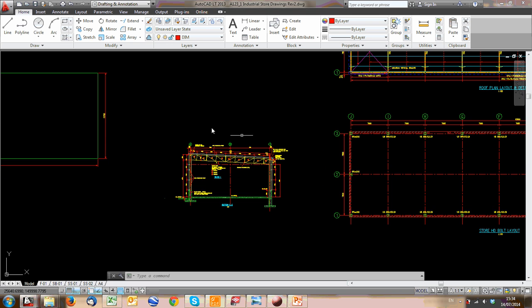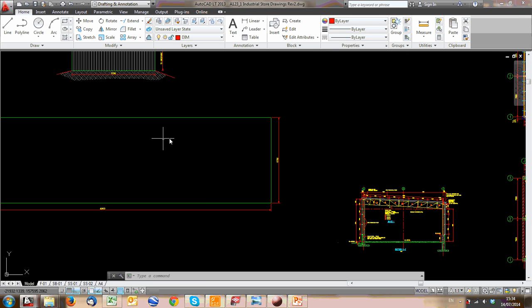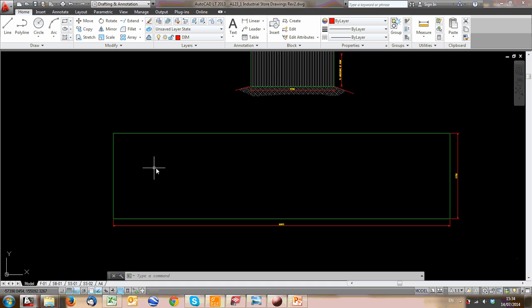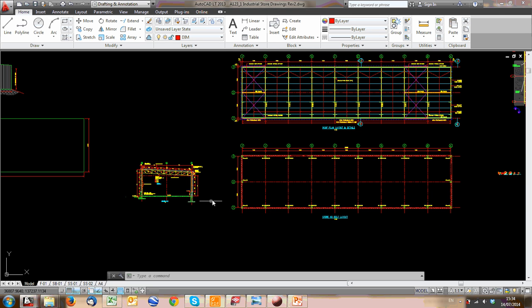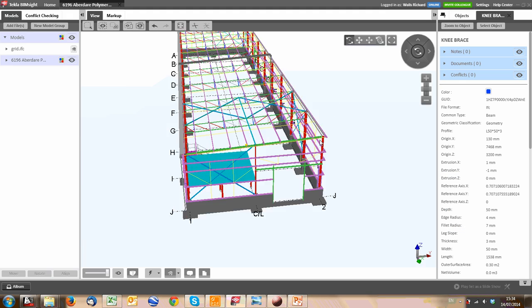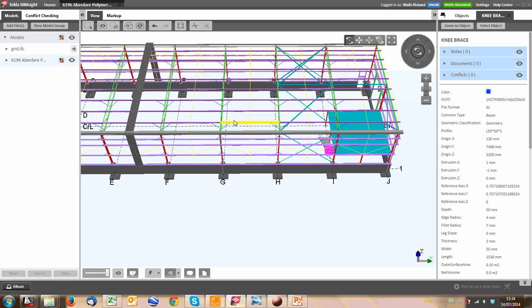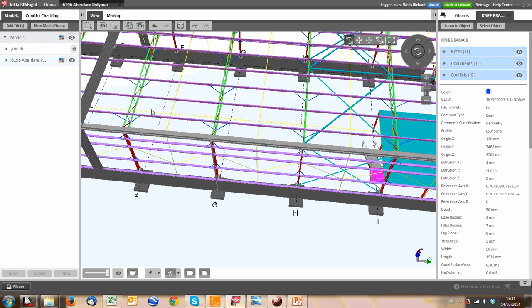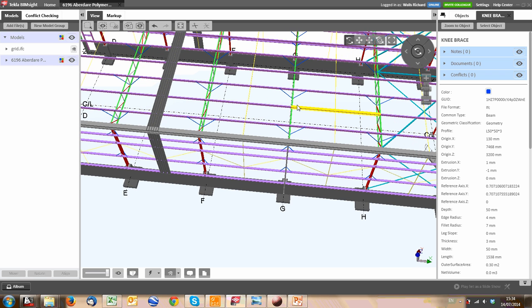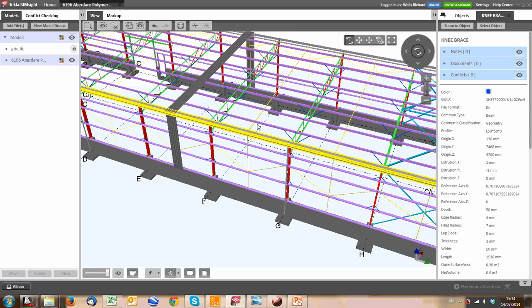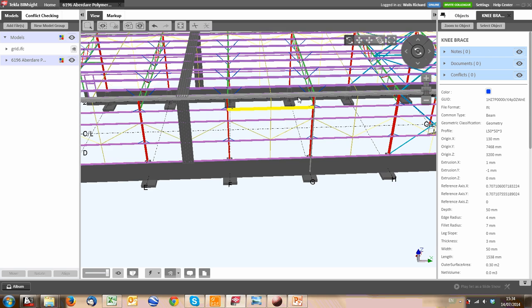to produce that? How are we going to get to this information here from a basic outline? Firstly, we need to know what distance our grids are apart. Normally for steelwork, for truss spacing, so I'm going to go to my 3D model here. These sorts of trusses, there's a truss, there's another truss. The space between trusses can range depending on the type of structure, what you're doing, layouts, etc. For something like this, between probably 5.5 and 7.5 meters is fine.